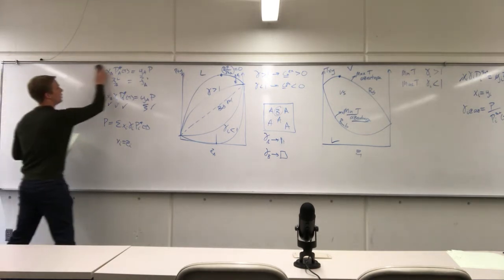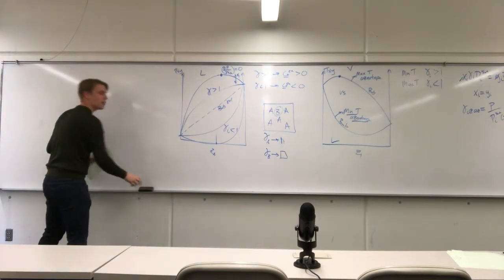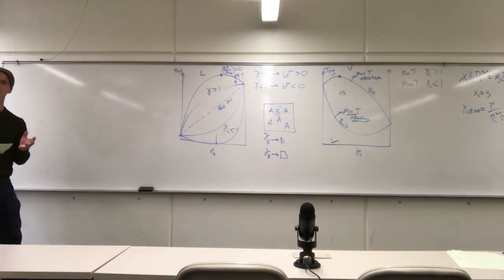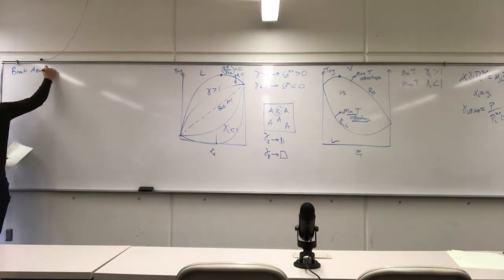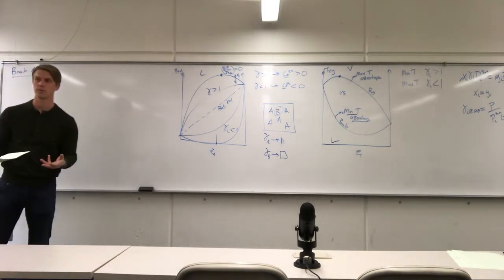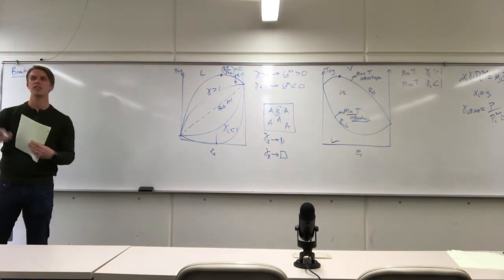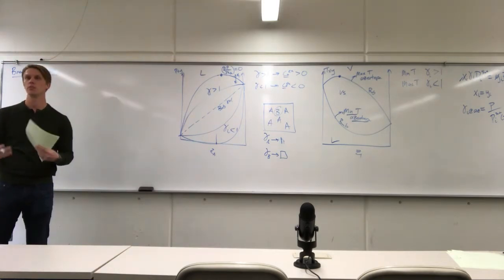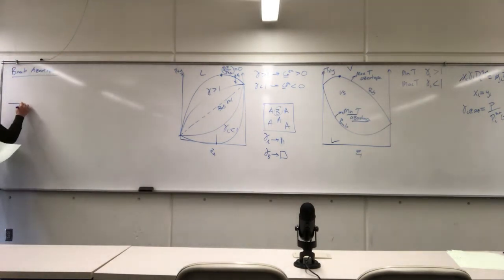Okay, so an azeotrope ruins your day. Well, it depends actually. An azeotrope makes your day if you're trying to tune an activity coefficient model, but it ruins your day if you're trying to actually do the separation. So how do we break an azeotrope? One way is you can actually turn a binary system into a ternary system. So you can use an azeotrope breaker that changes the vapor-liquid equilibrium, but then it adds an additional downstream separation that you have to do to remove your azeotrope breaking compound. The easier option is to use two distillation columns.